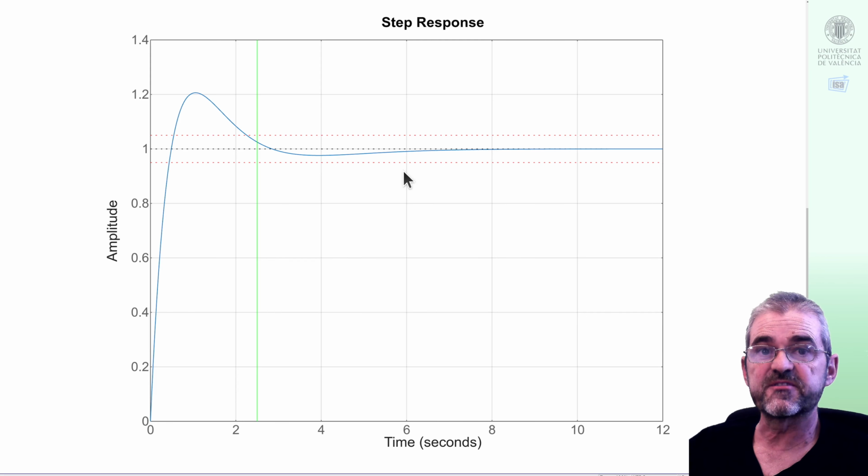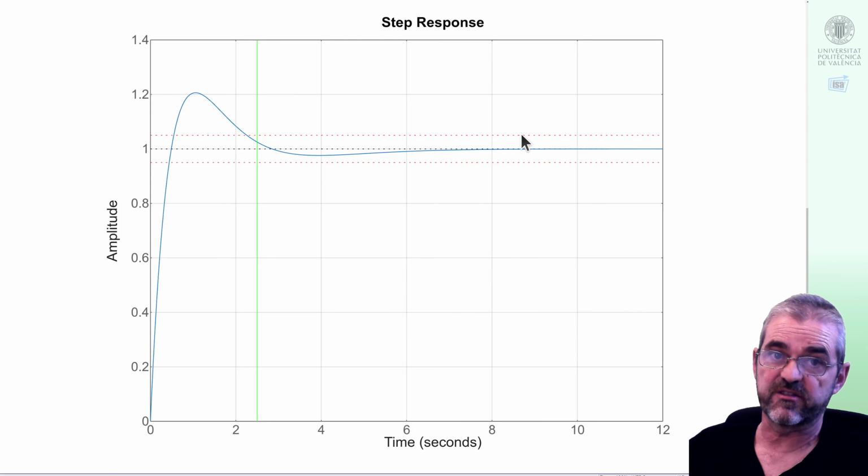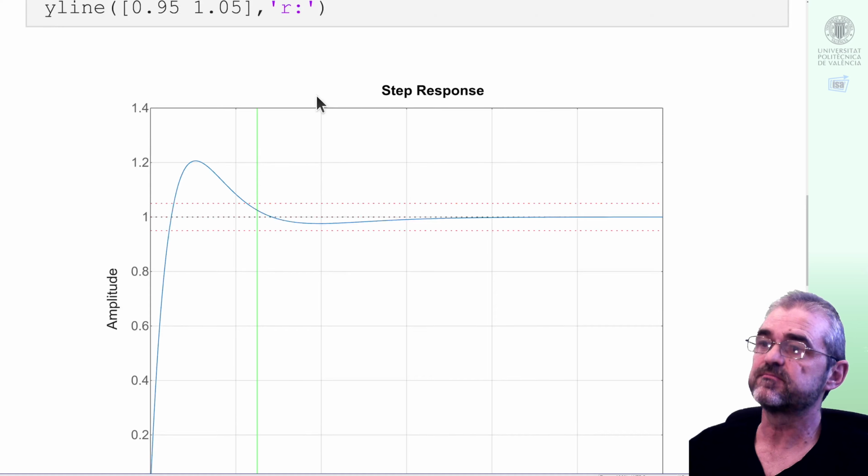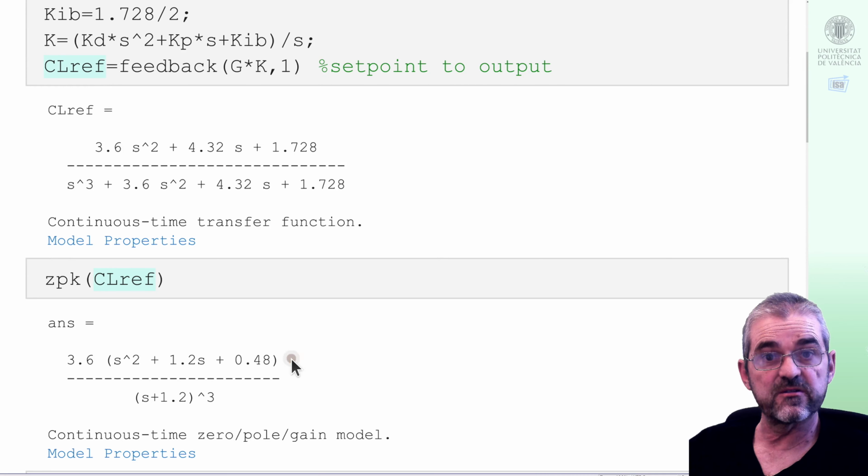As we have a couple of zeros in the numerator, strange things happen with overshoot because of the numerator terms. So this is a non-oscillatory transient, but it seems sort of oscillatory. Well, that's the effect of this numerator we are not allowed to analyze. And also we don't wish to; we'll fine-tune that later on with trial and error simulations.